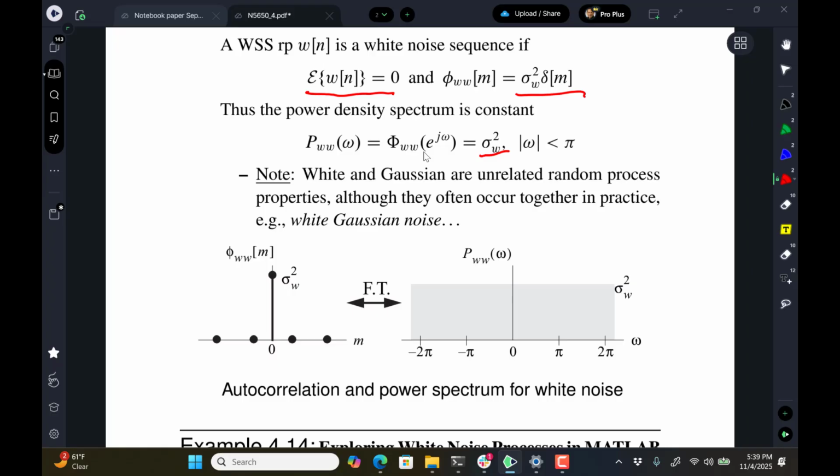In a physical setting, if it's off a receiver front end, the central limit theorem has made it look Gaussian because it's a superposition of all these random electron agitations. And you learned in probability and stats that if you convolve a PDF with itself over and over again, it eventually becomes more Gaussian shaped. Is that in your memory from that class? So that's where that comes from.